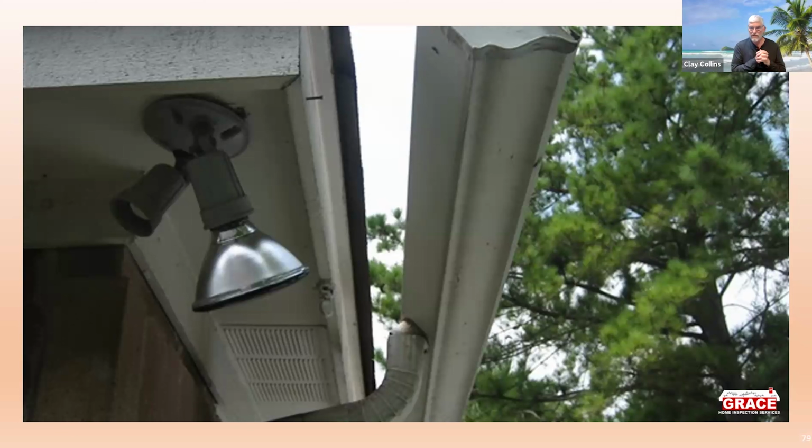I report that as deficient, because if it's pulling out, there's no way to determine how much water it's going to take in that gutter to cause it to completely pull out like this one. It also looks like, if that nail that I'm seeing down in the lower left corner of the fascia, and then I see a hole in the gutter itself, it looks like they might have used a typical finish nail to hold that in. And I think we can all agree that's not going to work.